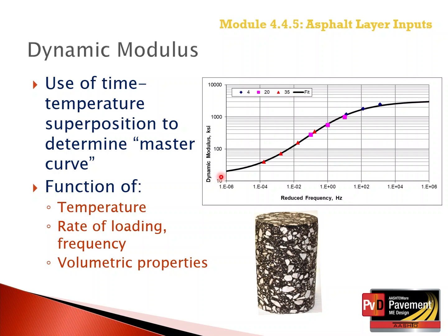The concept of time-temperature superposition is used to determine the asphalt layer stiffness for different truck speeds, with layer depth, and throughout the year and design period itself.